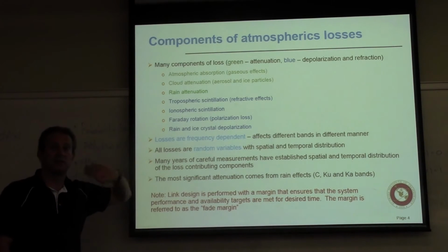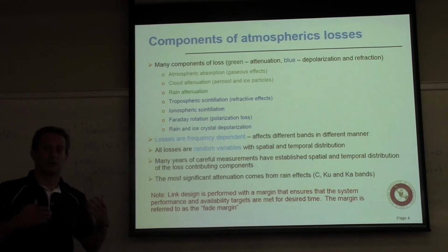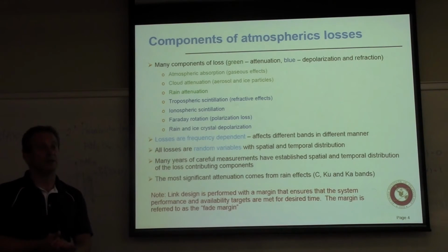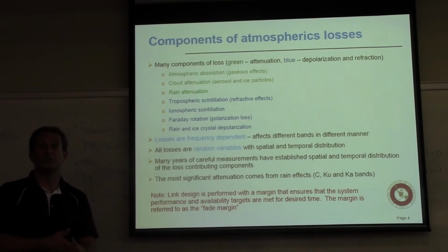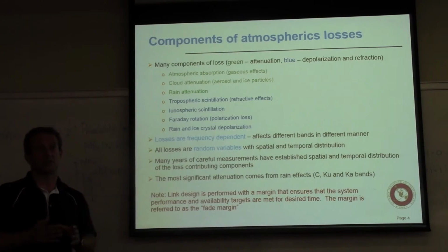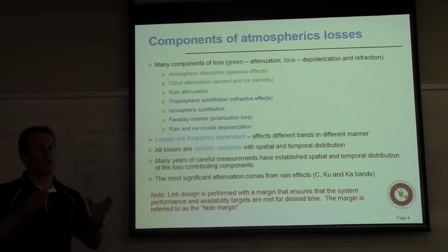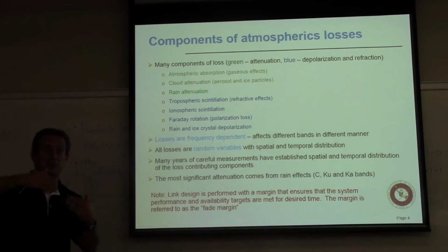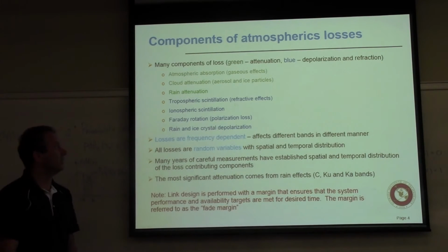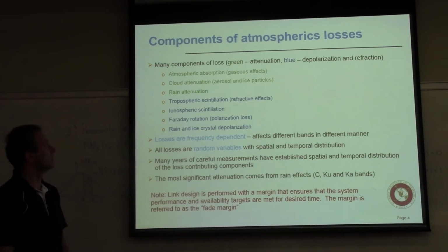Atmospheric absorption, that talks about absorption of the energy by the atmosphere itself. You will see that, as you know, the atmosphere contains gases. Those gases have resonant peaks, which are the frequencies at which they absorb the energy. If you happen to be operating on frequencies that are close to these, you're going to experience a certain number of dBs per the length of the distance that you propagate through the atmosphere.